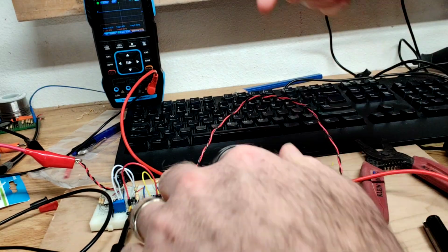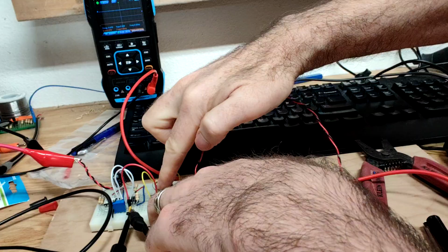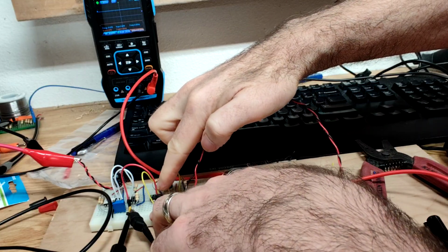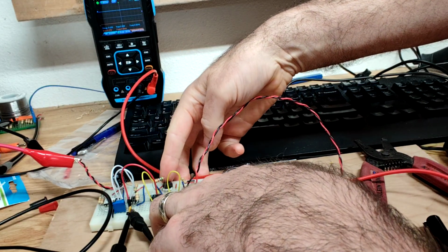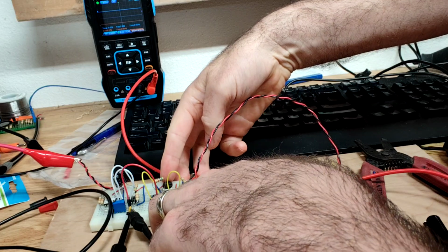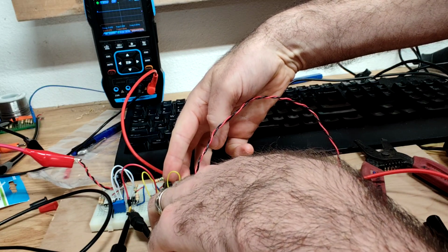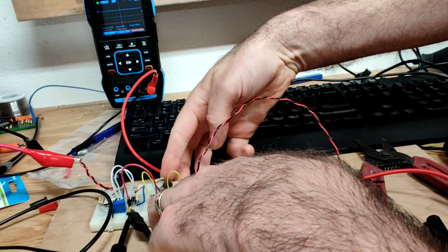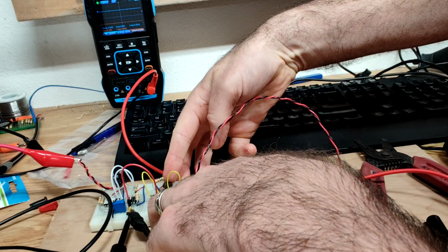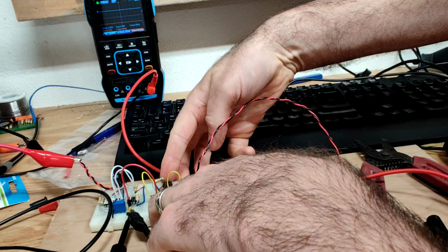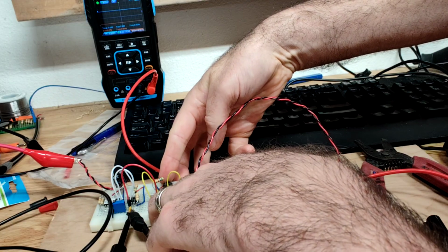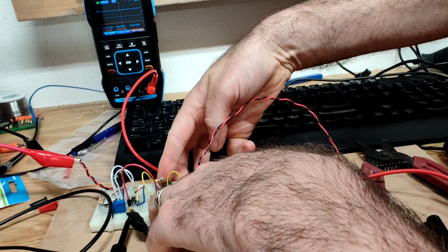Okay, so now I have the circuit wired up the right way so that it's going through this additional op amp here as a buffer. And so now when I turn it up, it gets louder and the pitch doesn't change. But do you hear how the quality of the sound changes? Down here it's kind of this pretty pure triangle, and then listen. As it gets louder, it gets more distorted.